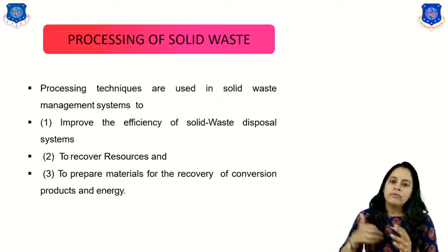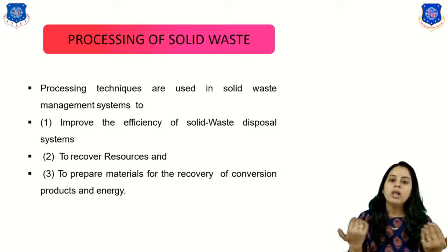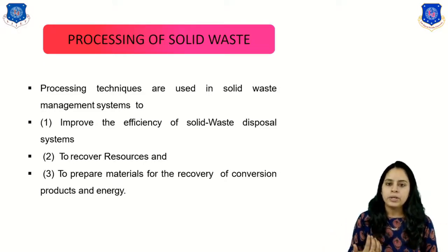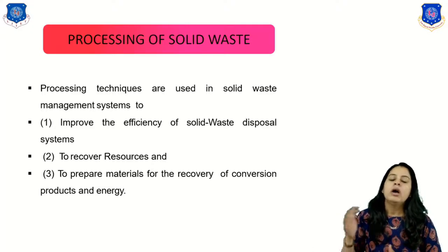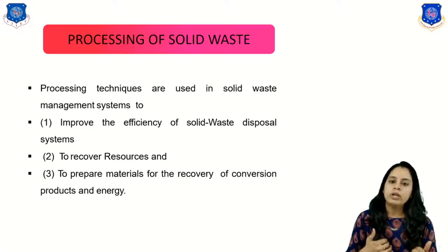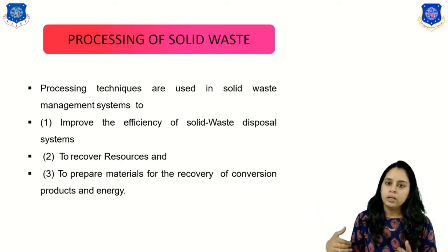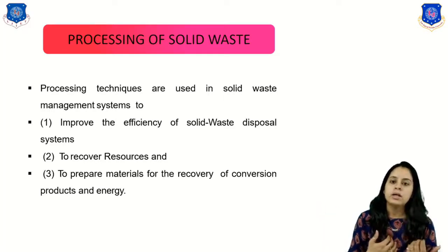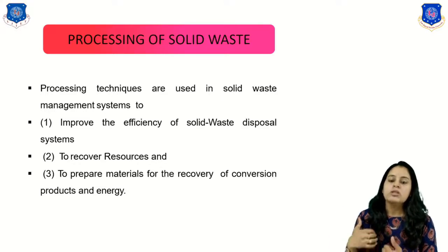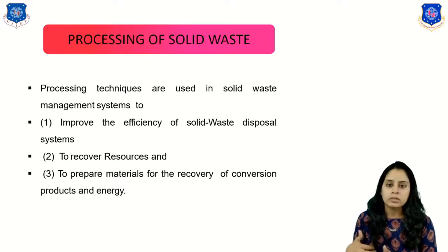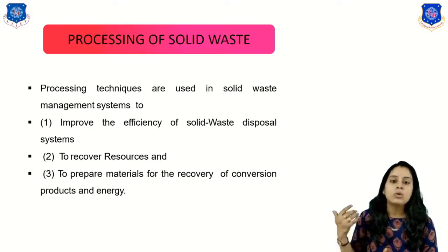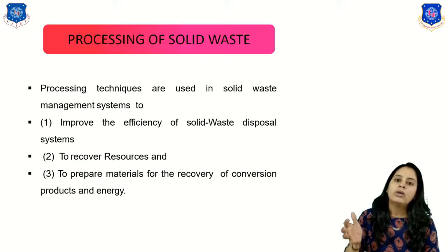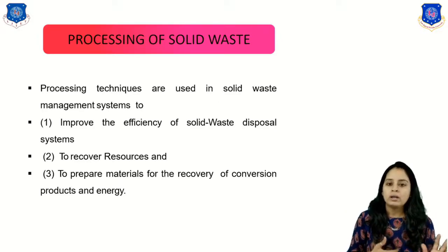For recycling and recovery, separation is required first. After the separation, some part of the solid waste goes to the recovery and recycling portion, and some part of the waste requires final disposal and goes to the disposal site. If I have 100% solid waste, then 40% will go to recovery and recycling, and only 60% will go to the final disposal. So this is the processing of the solid waste.